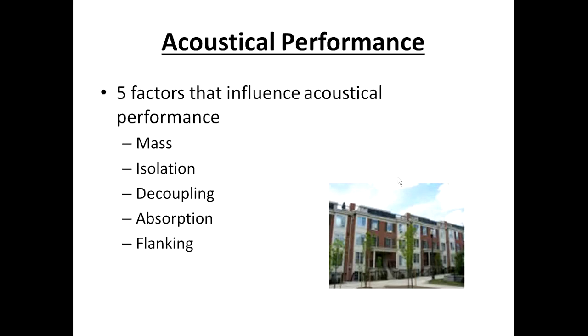And if I take that mass and divide it in two and move it apart a little bit, so they're apart from each other, I can increase the impedance, or the resistance, of sound to go through those two masses. If I double the single mass, I can pick up maybe 5 points of STC. If I double the distance between the two masses that I've put up, I pick up maybe another 5 points in an STC rating.